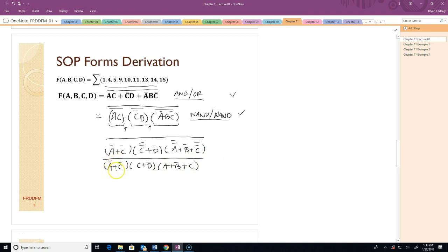I see some OR gates in the middle, so that's going to be an OR-NAND form. Okay, so there's the OR gates in the middle. These terms are being ANDed together with a giant overbar over it, which makes it into a NAND. Okay, so there's another classic form. Can't say I've ever seen it anywhere, but I certainly know how to generate it without too much trouble.